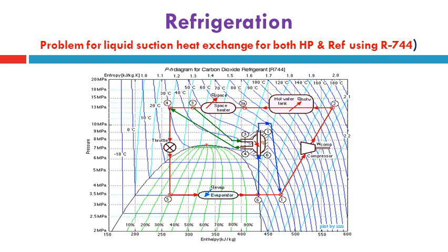problem, and also the work of the compressor, which is listed as adiabatic compression, not isentropic, so it's not parallel to the iso-efficiency line. We will take this into consideration in our calculations, and then the heat amount here and the heat amount here, and finally the heat to be removed from a certain space for cooling.